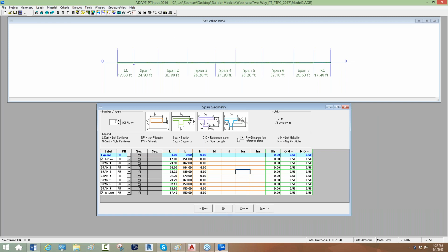So I recommend for reference height, if you needed a slab or step segments within a span, you can use this RH value to raise the slab vertically. It just offsets it vertically, positive or negative. For a flat slab like this, I recommend setting it equal to the height of the slab. That means that all of the control points for the tendons are going to be positive upward because they're referenced from this datum, this reference line here.